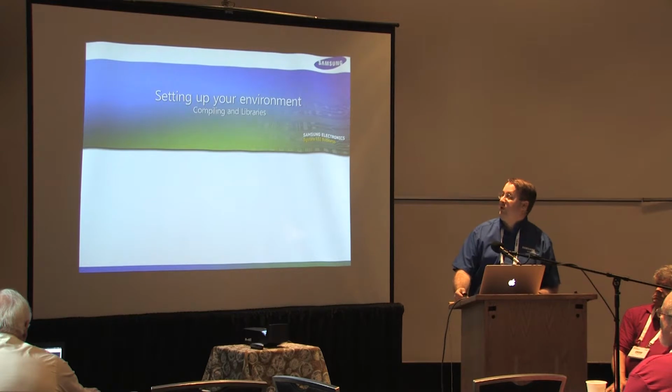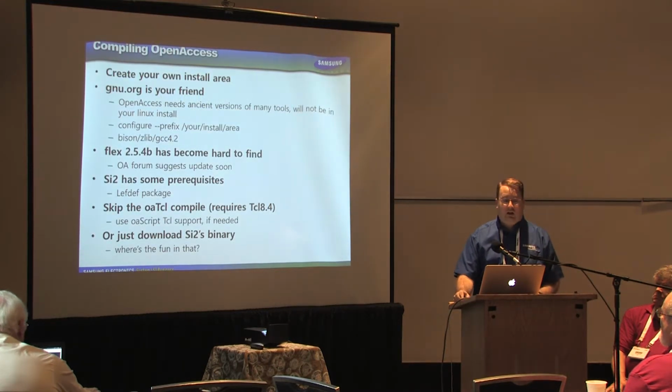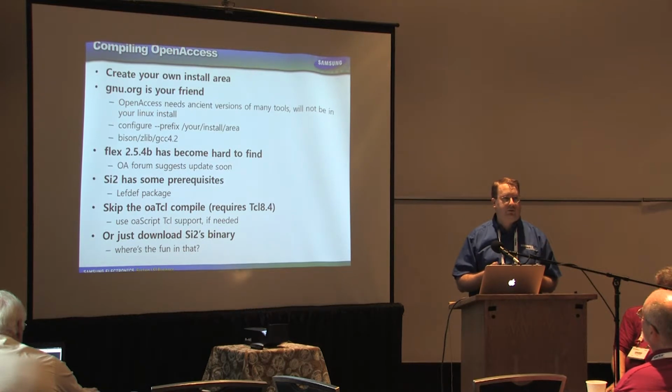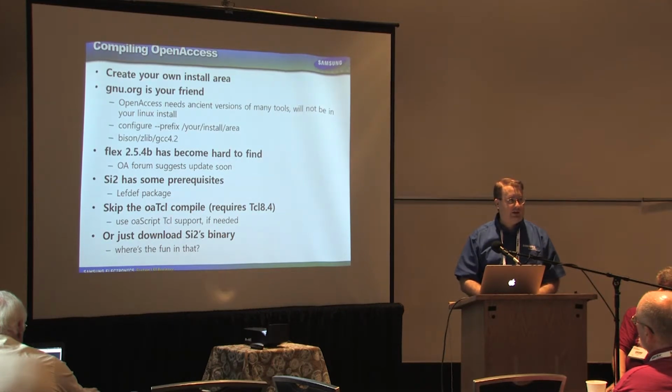So set up your environment. I recommend you create your own install area. Basically, you will be generating, compiling lots of open source tools, and they're honestly ancient versions of tools. You don't want to overwrite, even if you have root access, the current versions of your tools. Create a little home directory, installs, something like that. And this allows you to install the tools to help you compile open access, OA script and the leftdef package involved.